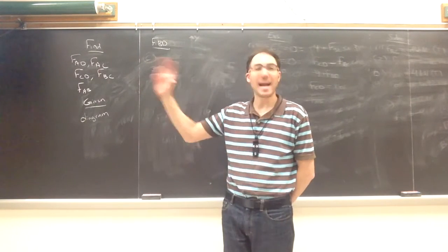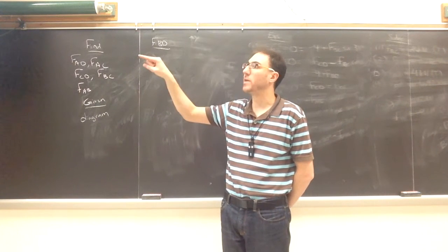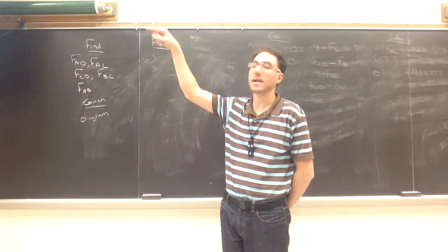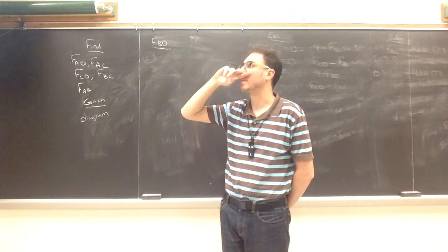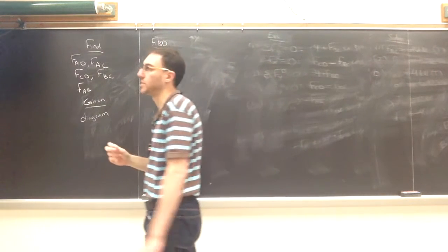If we look at the external reactions, we have a pin at B and a roller at A. So there'll be one reaction at A, and then a BX and a BY if we were to draw the free body diagram at B. So a total of 3 unknowns from the external supports.